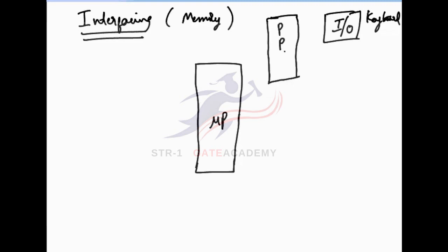That interfacing device is called PPI, Programmable Peripheral Interface. For this purpose, one IC is used, that IC is 8255. It takes the data from the input devices and connects the same data to the data lines. Any interface device is connected to the microprocessor through the data lines only. Again this data is connected to output devices through the PPI. PPI is used to interface input output devices with a microprocessor.